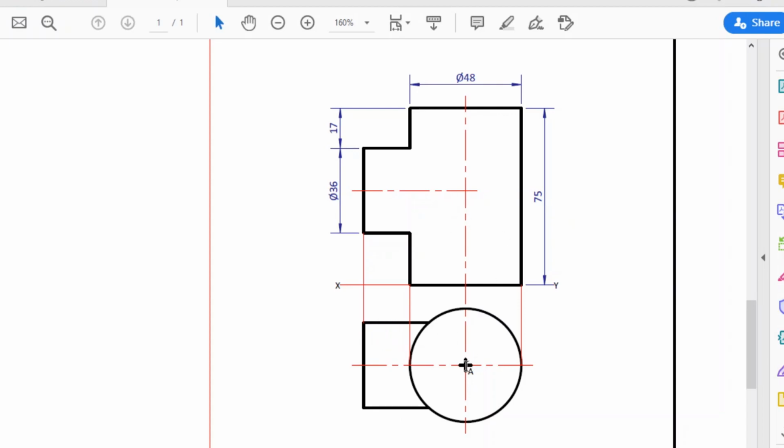So the first key to this entire drawing is that both pipes are round. The center of the main pipe is parallel with the vertical plane, and the base is parallel with the horizontal plane. And the two penetrate at a 90-degree or perpendicular angle. The distance from the center to the top is 17 plus 18, so that locates the center. And the distance from the silhouette of the main pipe to the end of that pipe is 20 millimeters.